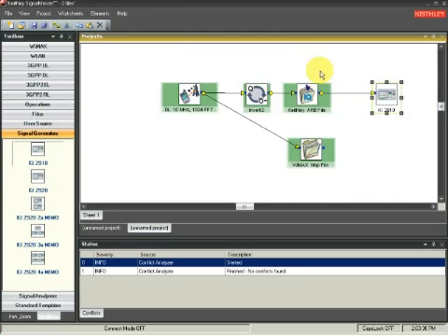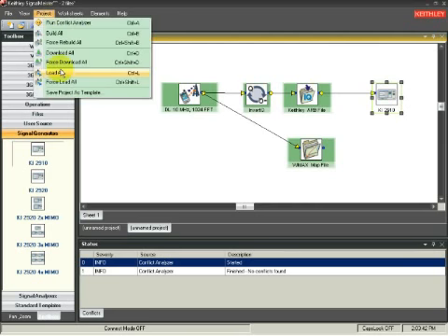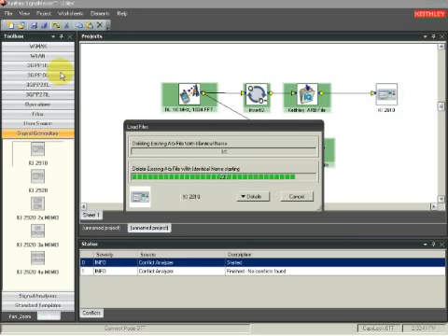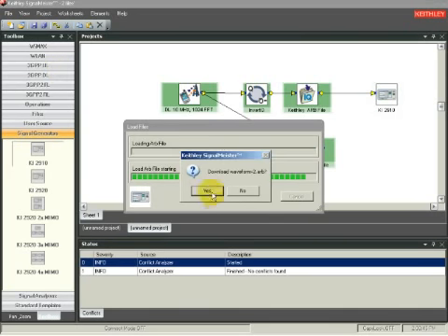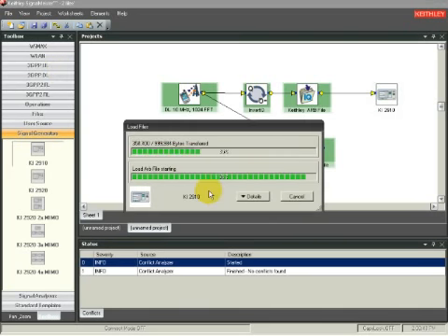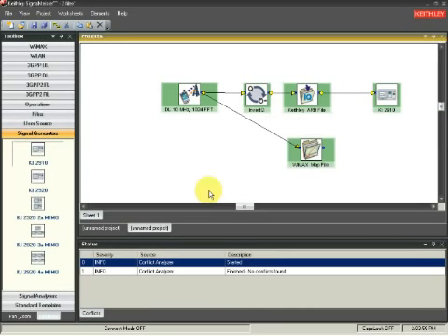Select Project and Load All, and the software will build the appropriate signal, download it to the instrument, and load it into the ARP. Download All will only build the signal and download it into the instrument, but not load it into the ARP. The file can only be loaded into the ARP if the instrument has the appropriate license.